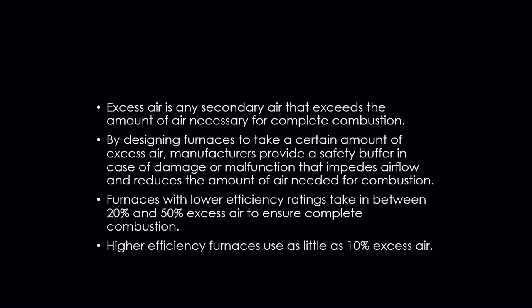Excess air is any secondary air that exceeds the amount of air necessary for complete combustion. By designing furnaces to take a certain amount of excess air, manufacturers provide a safety buffer in case of damage or malfunction that may impede airflow and reduce the amount of air needed for combustion. Furnaces with lower efficiency ratings take in between 20 and about 50% excess air to ensure complete combustion. Your higher efficiency furnaces can use as little as 10%.